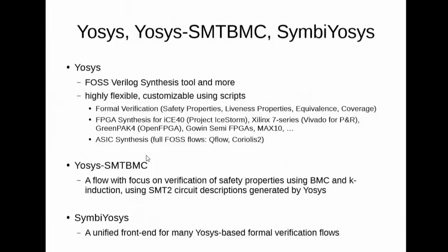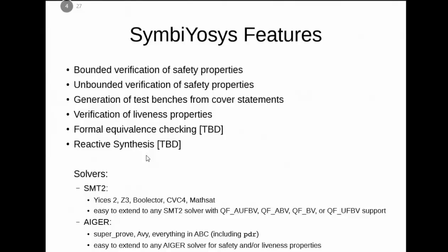And if you're using Yosys and YosysSMTBMC and some of the other tools directly, and you would like to switch from one engine to another, then you have to rewrite a lot of scripts and stuff like that. And SymbiYosys just takes all these things away from you, and you just specify what kind of engine you would like to use, and SymbiYosys knows how to do that.